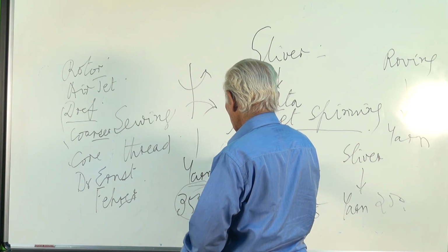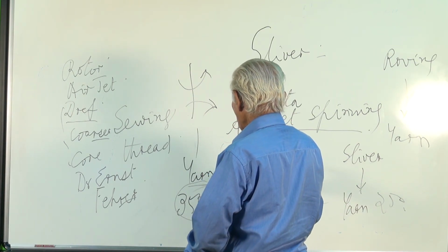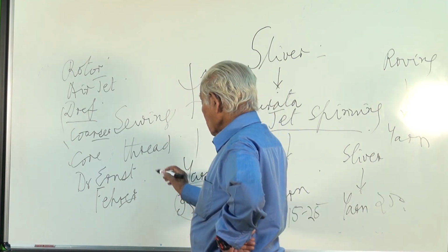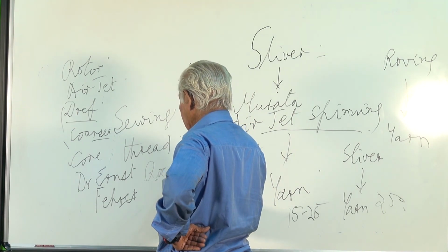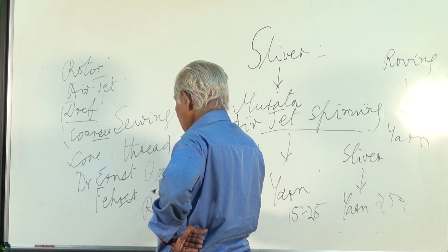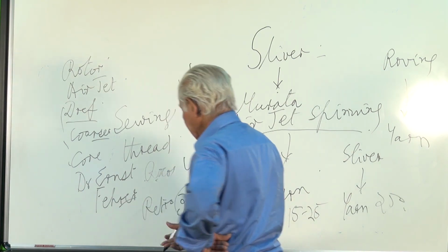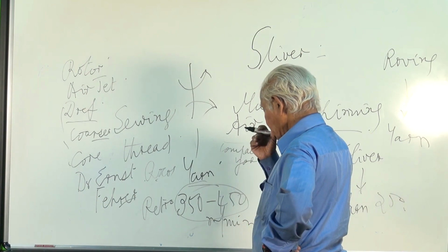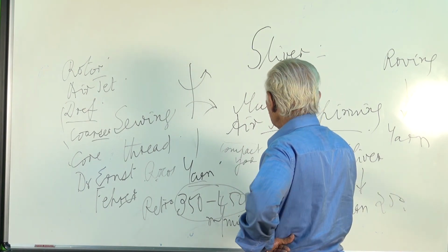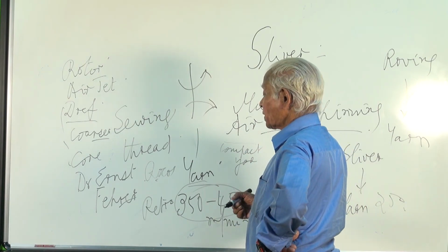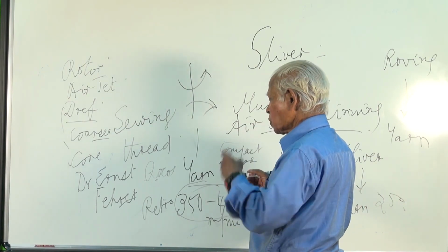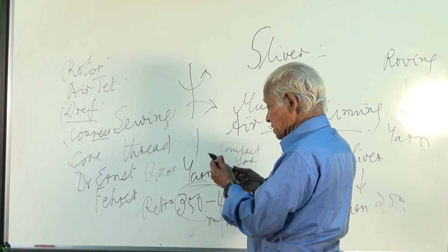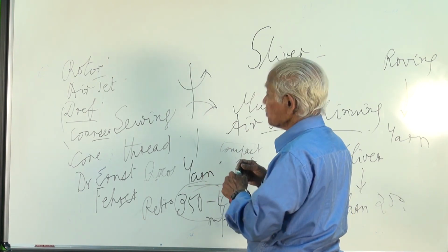and other technologies. And moreover, compact spinning can be fitted onto a ring frame, and ROCOS, I told you, can be removed or fitted. It is called retrofitted. Retrofitted means as and when we like, we can fit that attachment and then produce a yarn, and if not required, it can be removed also. That facility is available with this ROCOS spinning. And Vortex air jet spun yarns today have not become so popular, and maybe there may be better spinning systems which may come in the market tomorrow for the production of yarns.